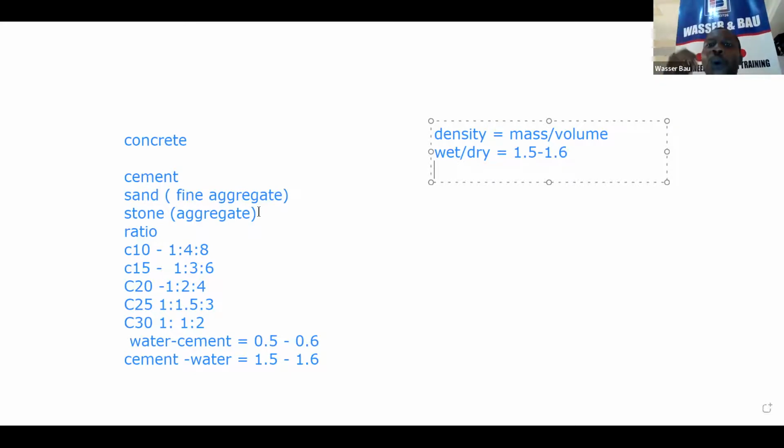For the volume, we know what we want to produce. Our volume here is 1 cubic meter. So our volume is fixed. Even if you ask me to get the volume for 100 cubic meters of concrete, my job is to get the value for 1, and then I will scale up. If we are casting 10 columns, each 2 cubic meters, we know we're calculating for 20 cubic meters. So for now, that boundary condition is fixed at 1 cubic meter.